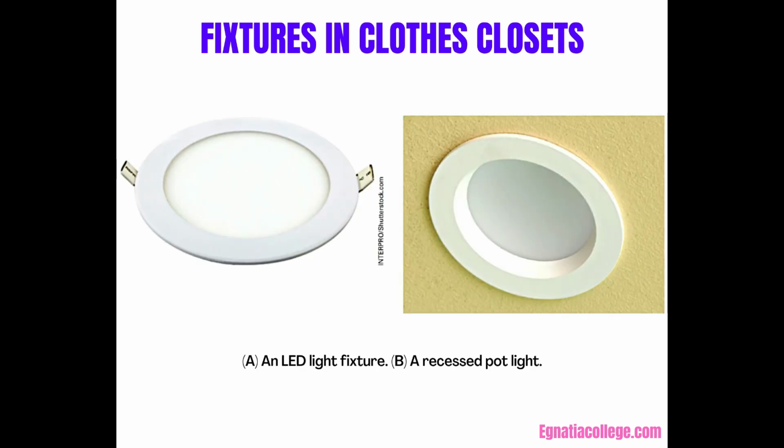The first floor electrical drawing shows recessed lighting fixtures being used in the closets as well as other areas of the house. These fixtures should be Type IC, approved for insulated ceiling use, Rule 30-906. When installed, these fixtures will be covered with a vapor barrier and blanketed with insulation. Because heat is not dissipated from insulation-blanketed fixtures as rapidly as from other types of lighting fixtures, a higher operating temperature will exist. Type IC fixtures include a thermal cutout device to prevent the maximum temperature from being exceeded.